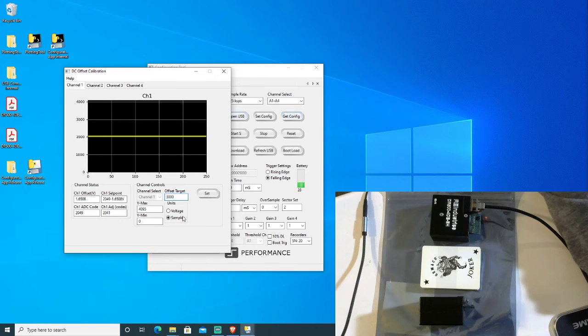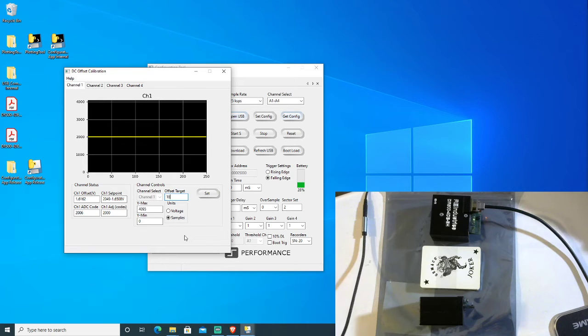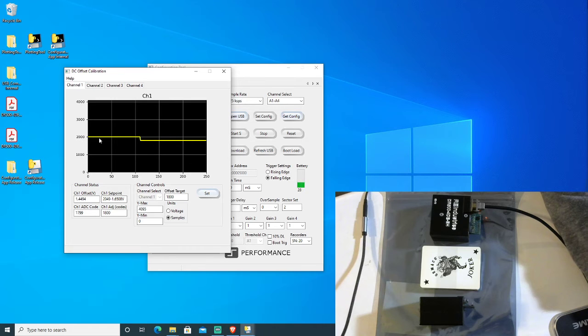So this allows customers to walk this up and down, and I'll touch on one of the main benefits here, probably the largest benefit of this functionality, besides it being so much easier to use and not involving external test equipment. One of the main benefits is that customers that have a lot more overshoot than undershoot can now walk this down to lower and lower values and can tune this DC offset so that they get the most information out of their waveform. And that's extremely helpful when you have a sensor. You want to be able to use as much of the signal it outputs as possible.